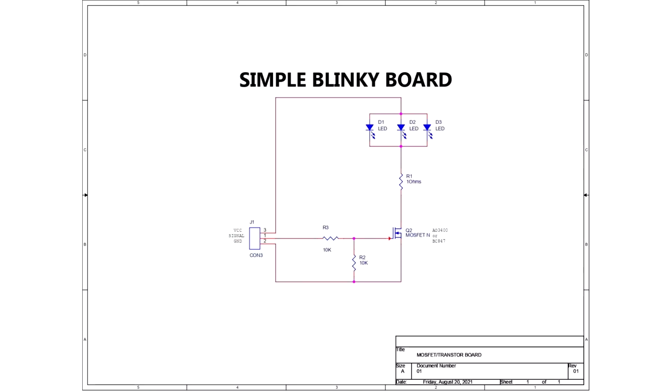As for its working schematic, I use this configuration which consists of 3 LEDs connected in parallel with the transistor. A load resistance is between them to limit the current a little bit. Then there's a 10K resistance on the base, and between base and emitter to ground the transistor's base whenever the PWM signal is not being sent to it.